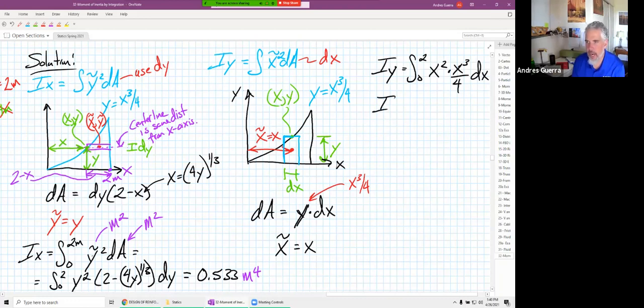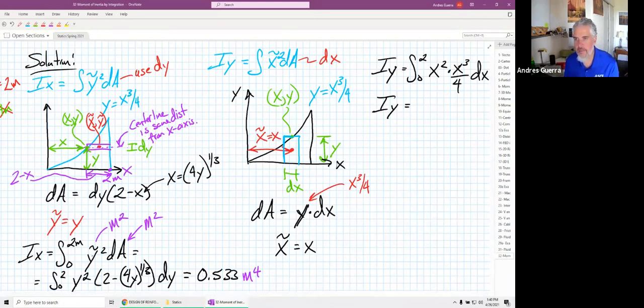And before I give us the value, or before you plug it into your calculator and come up with a value, think about the concept of what the moment of inertia represents, where area further from the neutral axis provides a larger bending stiffness, right? So I can't bend the yardstick this way, but I can bend the yardstick this way, right? I can go boom like that. I can't bend it that way, but I can bend it this way because I have more area from the neutral axis. Well, in this problem, it's whichever one has more area from the x or the y axis.